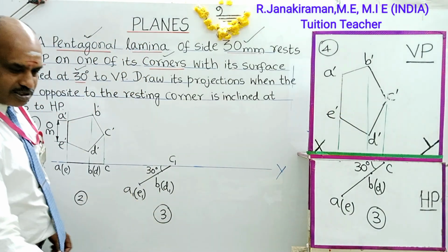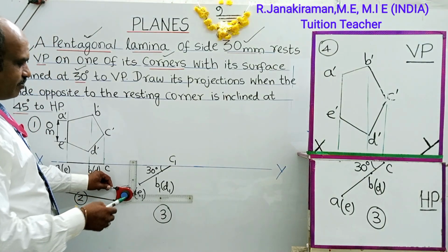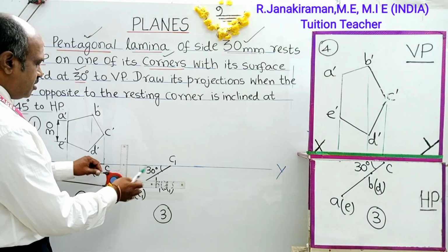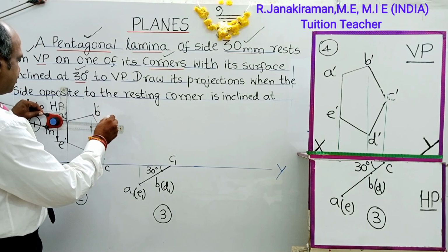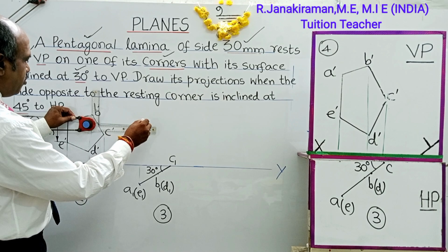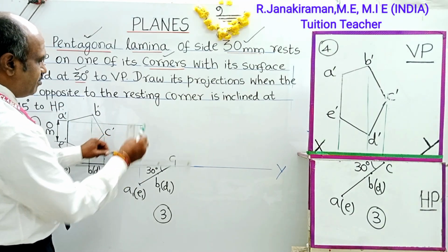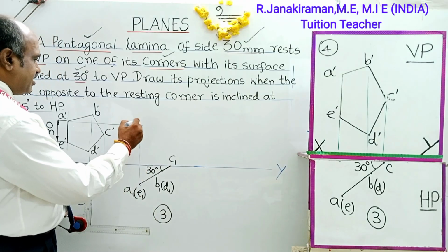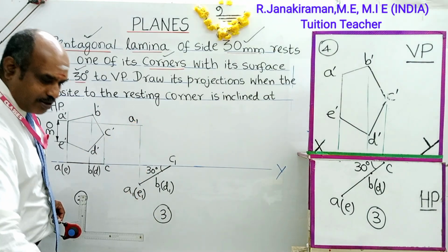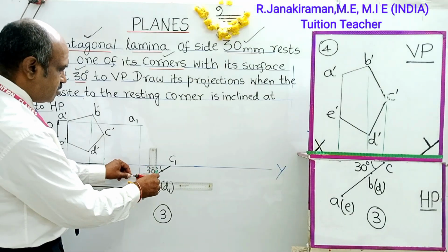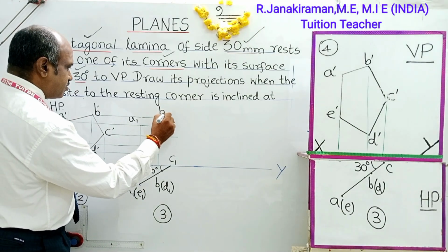How to draw this? Draw a vertical projector from A, then a horizontal projector from A dash in the previous diagram. From the previous diagram, okay, the horizontal A and vertical A intersect here. This shall be marked as A suffix 1. So this is a projection line drawn by using a 2H pencil. It's a lighter line. A, this is B suffix 1.